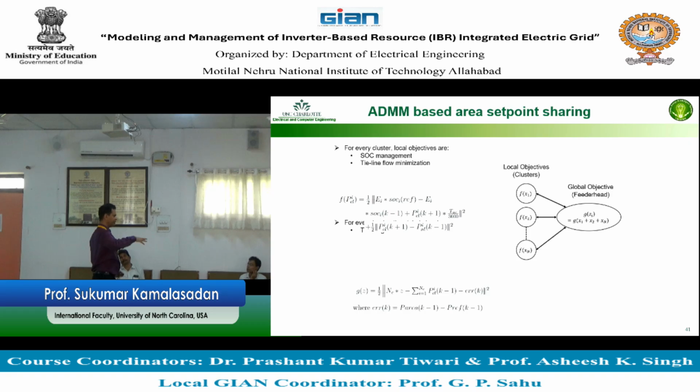So if the generation varies, you need somebody else to maintain that frequency regulation, which is basically DER. So the utility asks, for example, a battery or some devices to give extra power to regulate the frequency. In many places, the battery's value is only frequency regulation, especially in the US, because other people say that the battery doesn't have any value since I don't think a battery is needed for the PV farm.